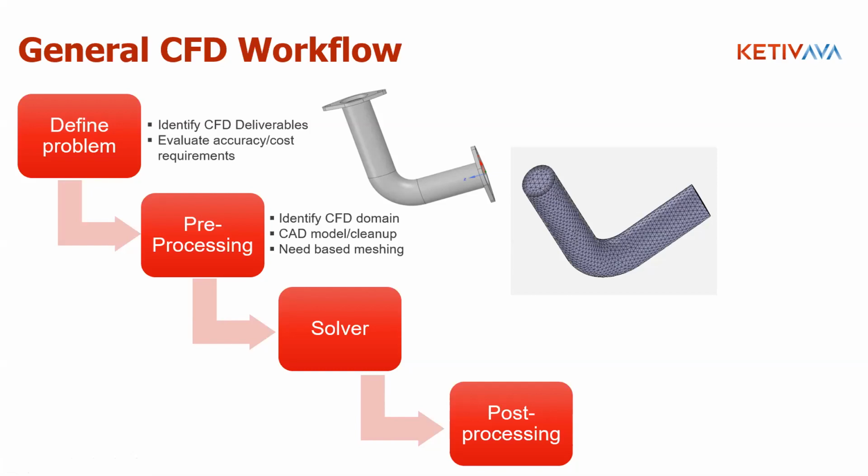If I wanted to simulate heat transfer from the pipe walls into the flow domain, then I should also include the solid domain in my model, right? So these are some of the considerations that go into defining the problem and the pre-processing stage.